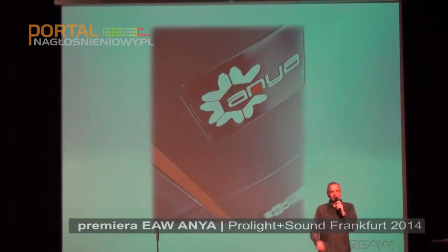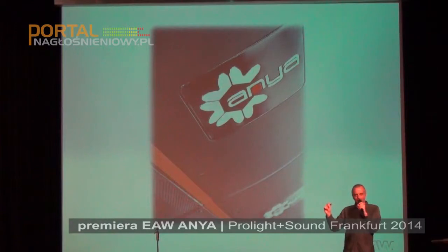At the factory, there is a final QC where every single device inside an Anya enclosure must meet a tolerance plus or minus in frequency response. This is absolutely necessary for directivity control and keeping the sound quality very high. Once those devices pass that plus or minus test, those reference curves are stored inside of the memory. Now it travels with the enclosure.